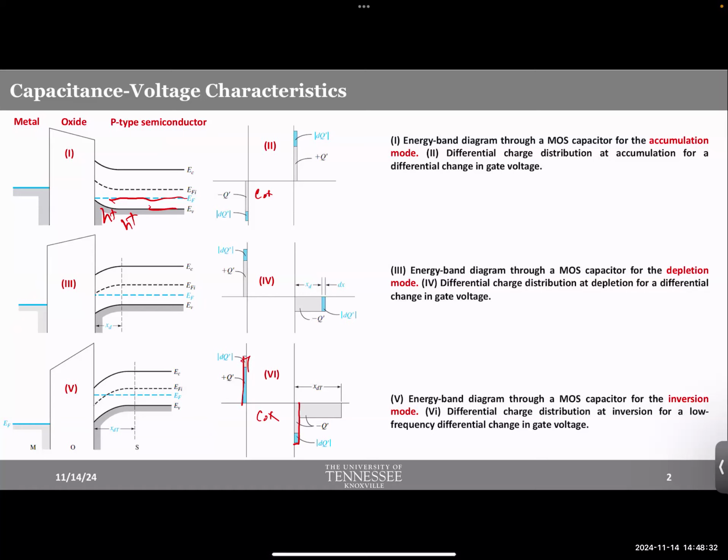Is it easier for us to pile up enough holes closer to the surface to create the capacitor? They're everywhere. I need 10 holes, come on, we are there. But inversion takes place through minority carrier pileup, which is electrons. There are few electrons in the p-type material anyway. So you have to collect enough of them to pile up and shadow the charge that you are providing here. Isn't that a slower process?